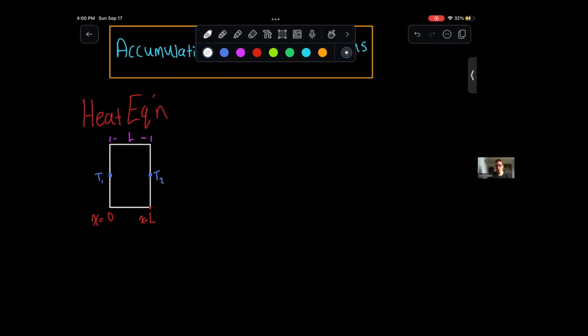Now, I want to find out how I can measure the heat exchange in this sheet. First, I'm going to start by asking myself, well, how can I measure the change in energy as a function of time? So over time, how does energy change? Well, we know accumulation, which is just dE/dt for energy, is equal to energy in minus the energy out plus the energy generated. And we're going to assume no energy is consumed. Now, something that I can do is I can change E to be Q. All that I have to do is recognize that there's no work being done in this system, and I can say, hey, E is equal to Q. So now we have dQ over dt.